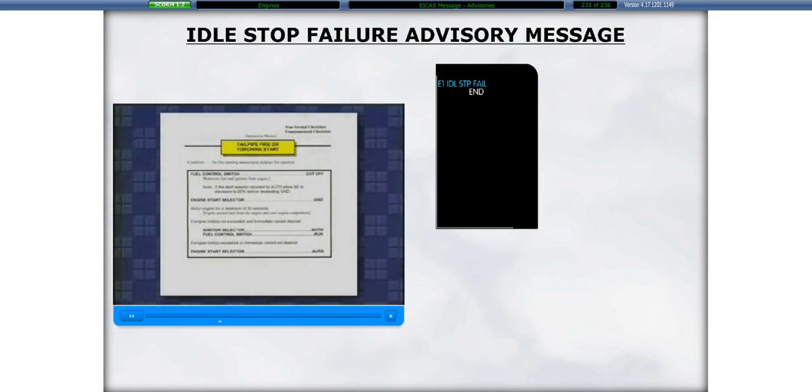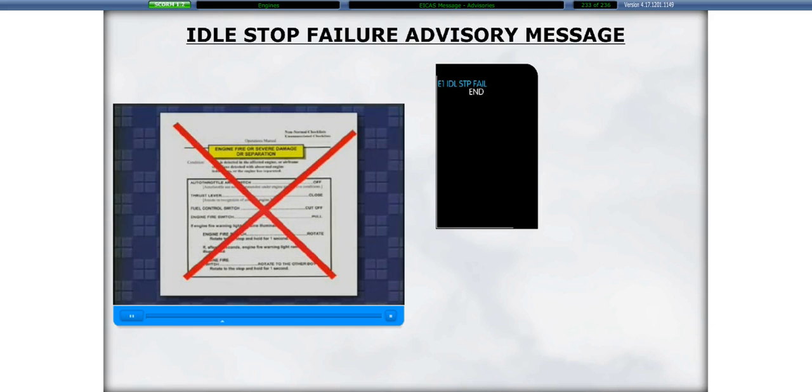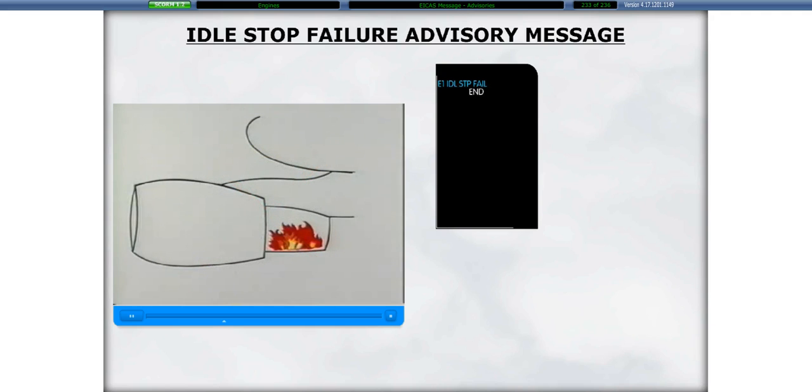If you are told of an engine fire without any flight deck indications of a fire, follow the engine torching procedure as outlined in your flight manual. This procedure will direct you to motor the engine and extinguish the flames. The regular fire procedure will not. Do not perform the engine fire procedure unless a fire warning indication occurs. Executing the regular fire procedure may disable bleed air to the engine starter and prevent you from being able to motor the engine to blow out the tailpipe fire.